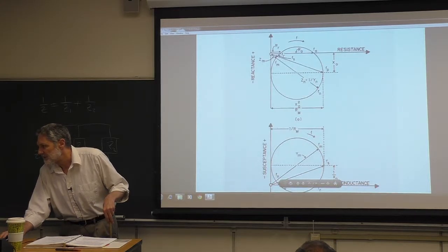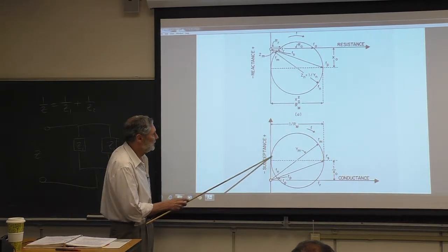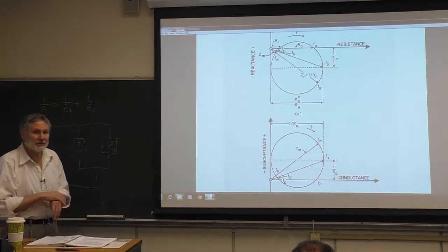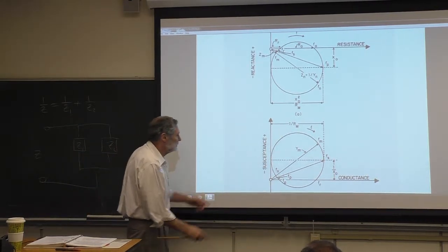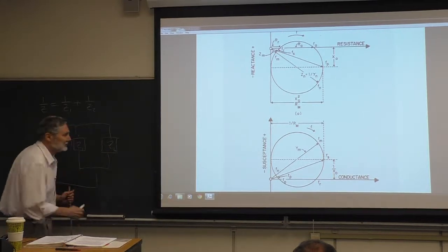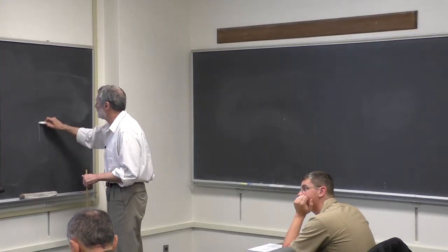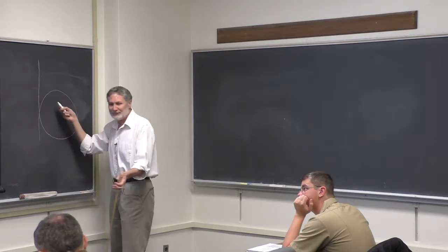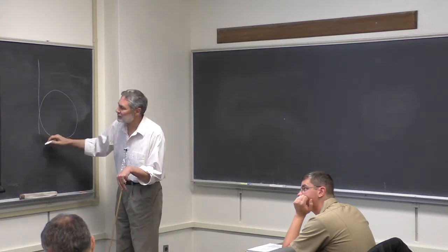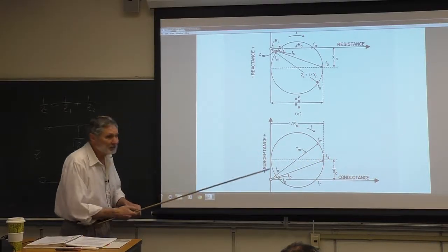So here's what happens for the admittance circle. It starts here for 0 frequency, goes up here, goes around there, and then runs off to positive infinity at infinite frequency. Okay, so from that fact alone, this can't be a perfect circle, right? Just no way. The curve is a nice smooth curve, and it looks like this. So this can't be a perfect circle. It absolutely cannot be, because this is a very smooth curve here. So wherever this starts, okay. We'll see that evidenced in some graphs later. But anyway, it tends to be very close, which is nice.